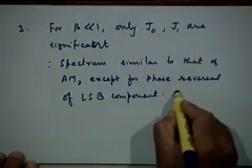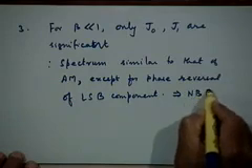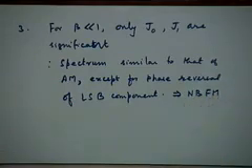Right, and this is called narrow band FM. Narrow band FM, which is the FM defined to arise when beta is very small, has a spectrum similar to that of an AM signal, in the sense that it has only the same two sidebands, Fc plus minus Fm, with this difference.